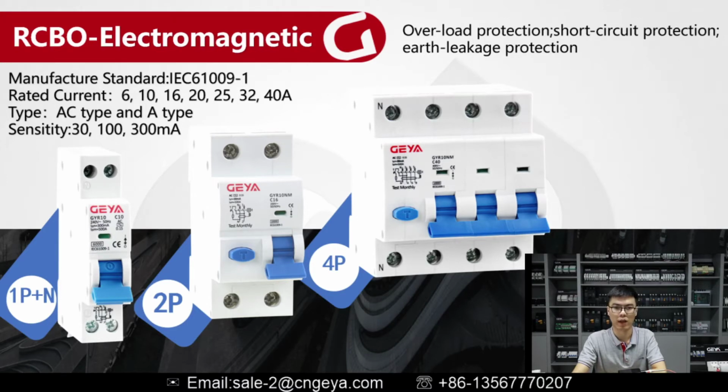You can see we have 3 different models on the structure. First one, it is 1 pole plus a neutral terminal, and the second one is double poles, and the third one is 4 poles. Its manufacturer standard is IEC standard, and rated current we can do is 6, 10, 16, 20, 25, 32, and 40 amperes.